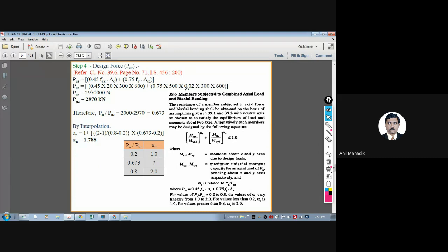So Ac here you can see, Ac how much? fck you know, Ac means area of concrete, 300 by 600. What is Asc? Area of steel. How much is our area of steel? We have assumed 2%, right? So how much will this be? Yes, sir, 2 upon 100 into 300 by 600. So 2 upon 100 means 0.02 into B into D. So this is your actual capacity.